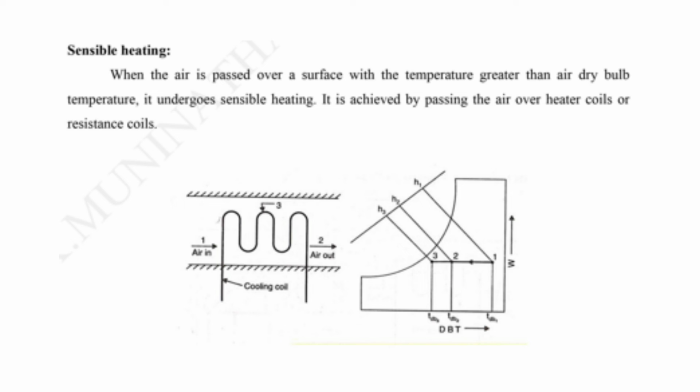The air initially supplied from the normal atmosphere is shown in the psychrometric chart on the right hand side, where we are able to calculate the dry bulb temperature from the enthalpy value, as well as the W value, which is obtained from the vertical axis.